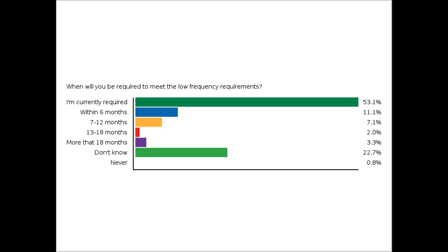But of course, there are always situations where, if you have a retrofit application where you're doing a massive teardown, the authority having jurisdiction does have the discretion to require you to bring that whole building up to the latest code. So I would strongly suggest that you consult with your AHJ whether that project is going to have to comply with the new low frequency requirements. Yeah, when in doubt, always check with your AHJ. I think that's something we say on almost every webinar.